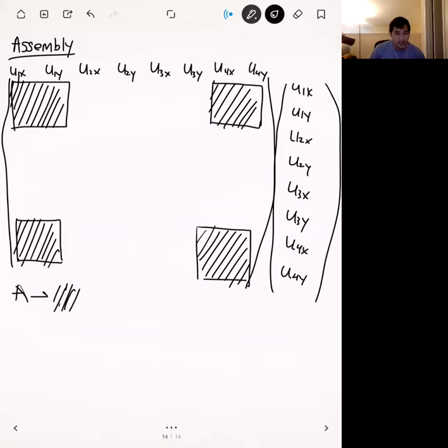Okay. And so that's where you would insert element A. This one's going to get a little bit messy because we have so much converging on node 4, but we'll see. All right, and so element B, let's do bubbles. Element B acts on nodes 2 and 4, and so we're going to have the 2, 2 block. There's going to be this one right here.